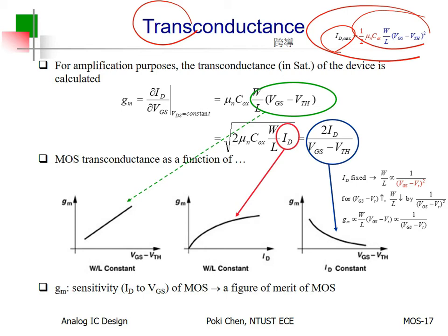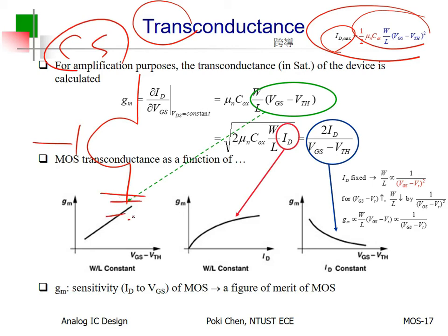You apply your signal to the input, but you get the output signal from the other point, the other port or the other node. So you can see for the MOSFET, usually for common source, yeah, common source is the commonly used configuration. Source as reference, you apply your input to the gate and you get your output from the drain. So input port here, output port there, they are not the same. So we have transfer.